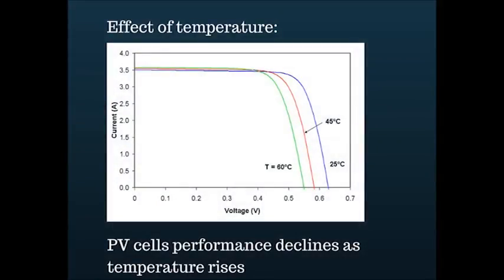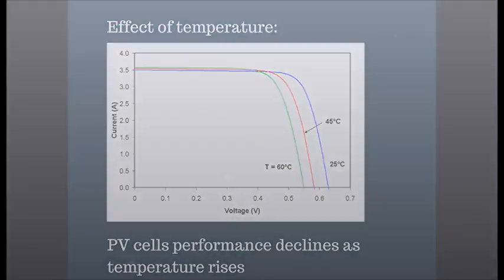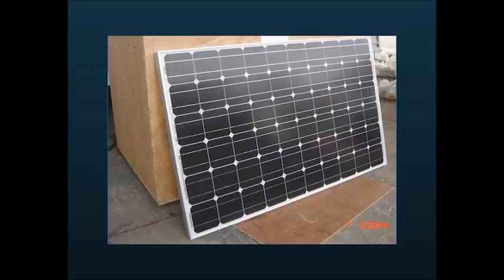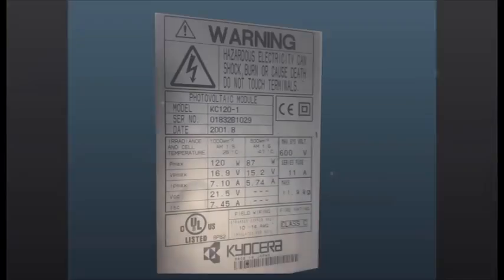It is important to understand the relationship between temperature and voltage. While temperature does have a slight impact on current, it has a large impact on voltage. Now, what are the PV terms you should know for design purposes? You need to understand the information delivered on the module's specification sheet.